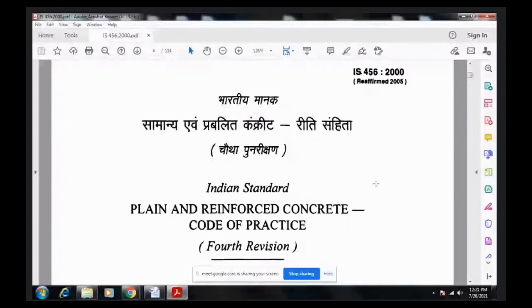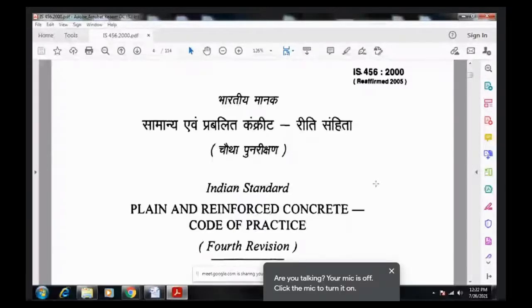Then they will ask you what kind of reinforcing steel bars you are recommending. Is it a mild steel, or is it a high strength deform bars? And there are different qualities of high strength deform bars. Which one? Is it 450 or is it 500? So they will ask you this question. So you have to give the specification of the material.